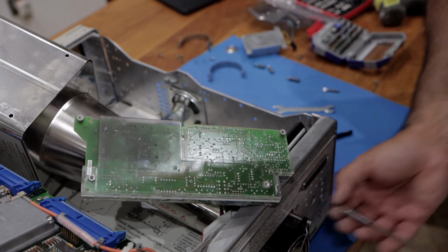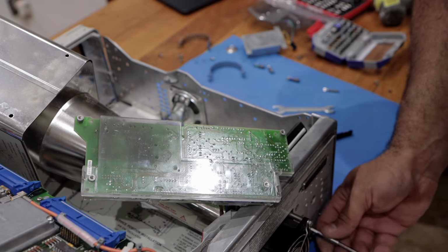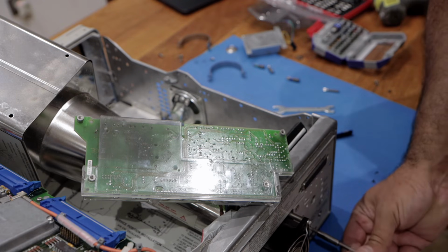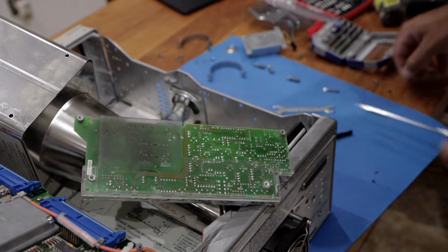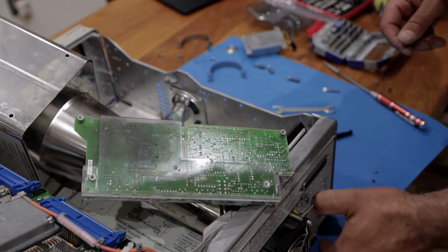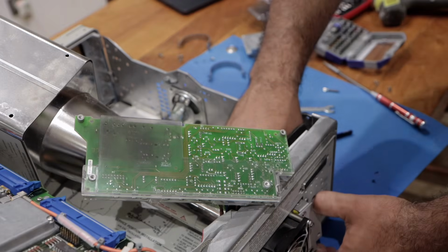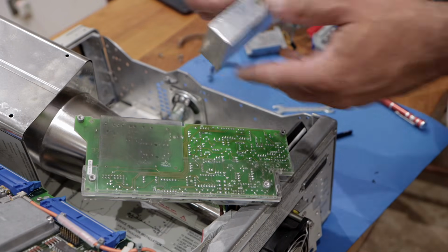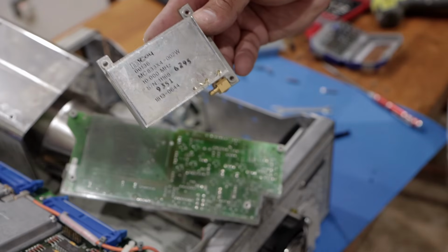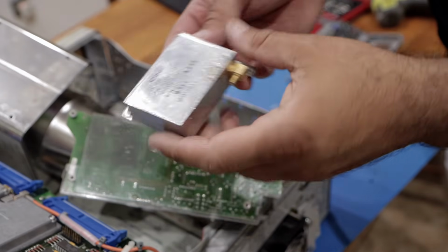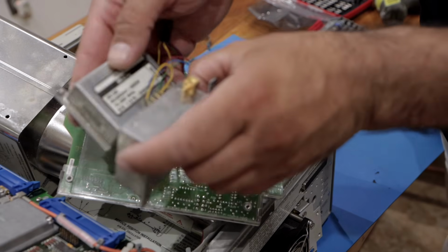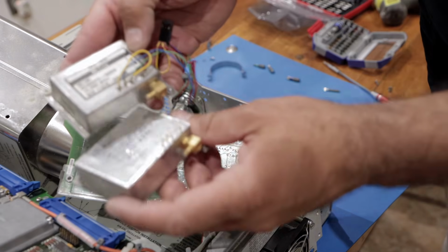From the top side, I remove the CRT again to get easy access to the 821 oscillator. I also had to take out the battery holder from the back just to reach the SMB connector. I later realized I didn't actually need to remove the CRT for this job. Maybe I should have double-checked the service manual first. And here it is. This old oscillator has more rectangular edges compared to the new one I received. Side by side, they look almost identical, so fitting the new one in place should be straightforward.